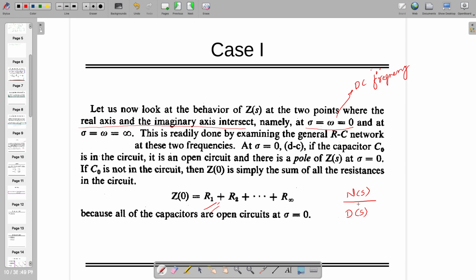And similarly, if you are designing RC admittance, then there might be the case that if numerator has one extra entry than denominator, sorry, it has to be reverse, then you are going to observe pole at origin. Pole at origin in impedance function means it's going to give you a capacitor. No, 1 by... in impedance. In impedance, you are going to see capacitor, right?